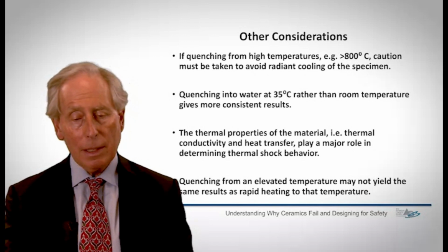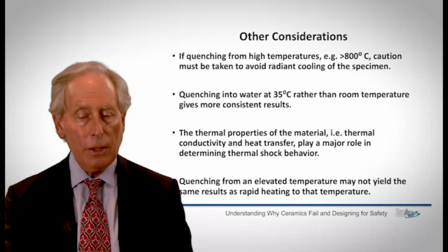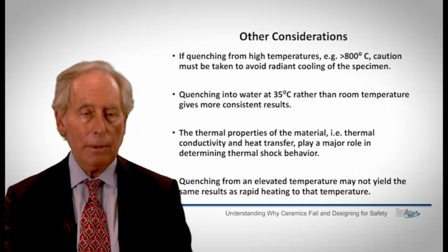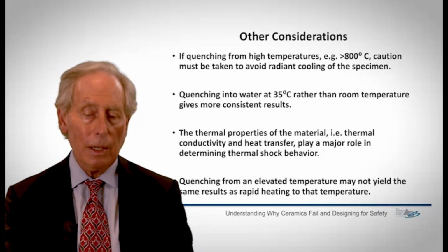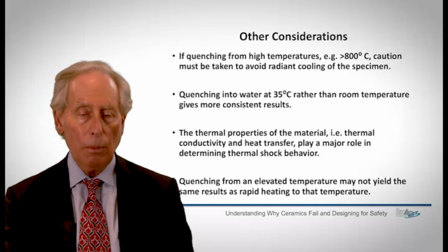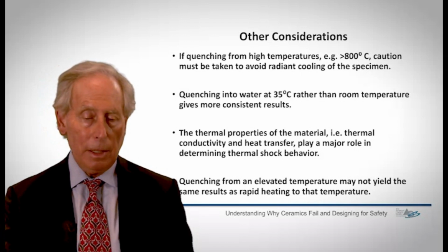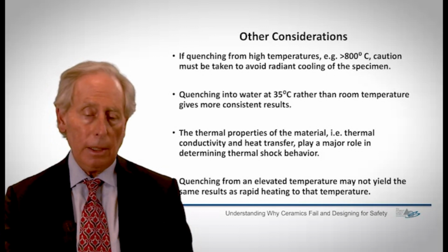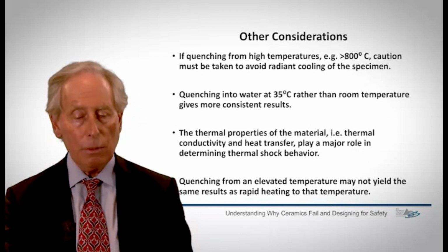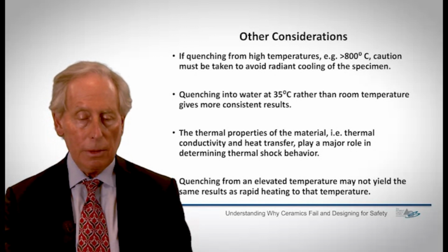I want to point out some other considerations before I finish. If you're quenching from high temperatures, you've got to be careful that you don't get radiant cooling of your specimen when you take it out of the furnace before you put it in the quench medium. In other words, you think you're at 800 degrees C, but if you wait too long to put it in the quench medium, you might be at a different temperature. I mentioned earlier, quenching in a little higher temperature water than room temperature gives more consistent results, and there are references at the end to some of those studies.